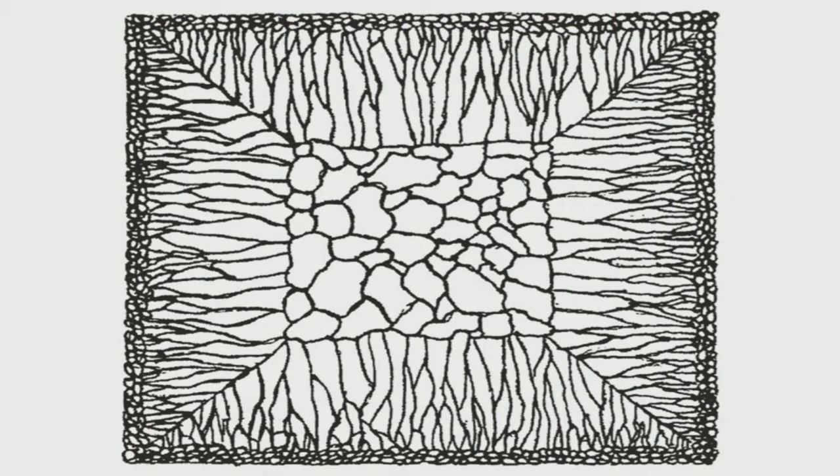Now, let us look at how the solid structure actually looks. I have told you that there are two broad areas in the solid structure. Look at this, these are the mold surfaces here, here, here, here. So, we have columnar grains initially, but look here, just at the mold surface, because of the chilling effect people say there are fine equiaxed grains just at the surface. Then once solidification goes ahead, just after a fraction of a second, the columnar dendrites increase in columnar fashion, and the primary dendrite goes on increasing in length.